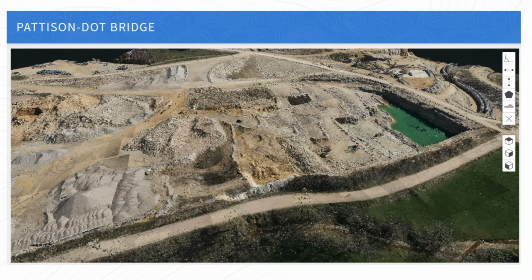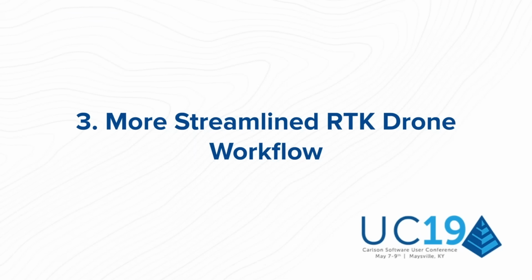But there's a sweet spot where you can get all those vertical facades, but not really have any degradation of point cloud quality, and that's in that 25 to 35 degree off nadir range. So that's our recommendation. But very good question. I wish I had some slides in this presentation that went over that, and I took them out.